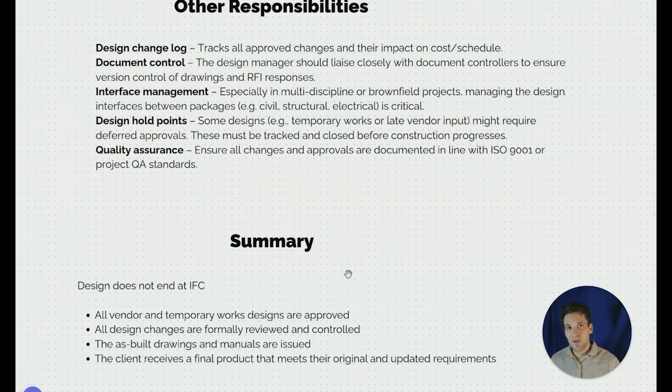Okay, so just a brief recap. As we've established, the role of the design manager does not end at the IFC stage. All vendor and temporary works designs need to be approved. All design changes need to be formally reviewed and controlled and assessed and approved. The as-built drawings and operations manuals need to be produced, and the client, at the end of the day, wants to receive a final product that shows their original requirements have been met.